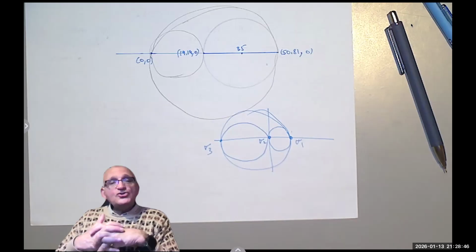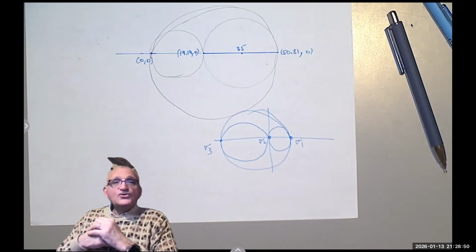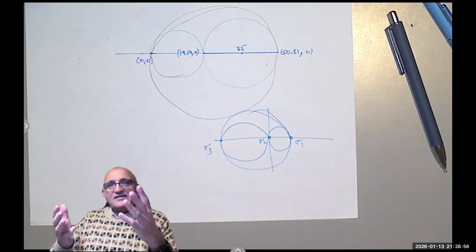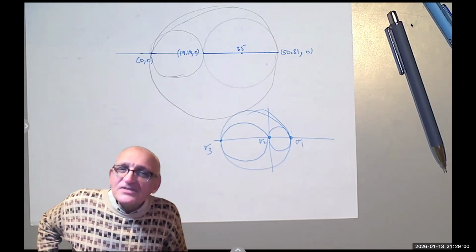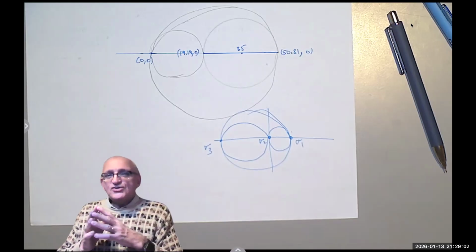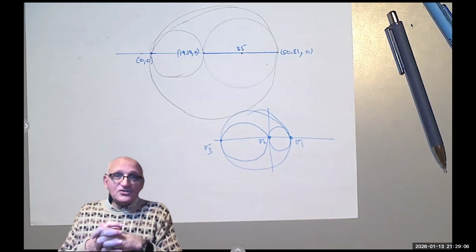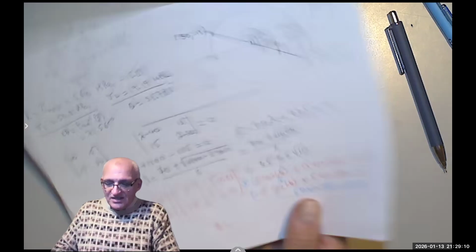You can also use a 3x3 stress tensor and solve for eigenvalues and eigenvectors. Most of the time whoever makes the problem makes it easy, but it would be more cumbersome to find the principal axes using eigenvalues, because it's a 3x3 matrix, not a 2x2 like the one we did last time.